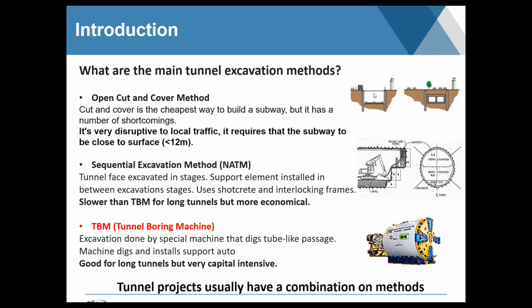It's probably the easiest to understand. You basically have a deep excavation, you install your structure, and then you refill or cover the tunnel once it's in place. It has its advantages in the sense it's probably the most economical, but in urban areas, it's going to be the most disruptive, especially for traffic. And it requires the tunnel to be close to the surface.